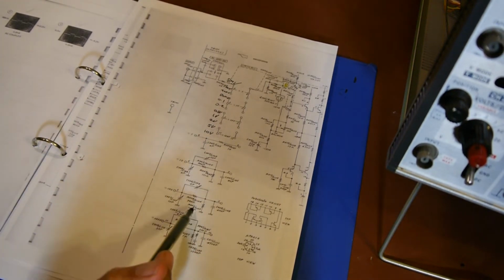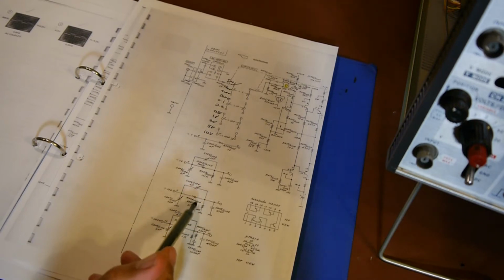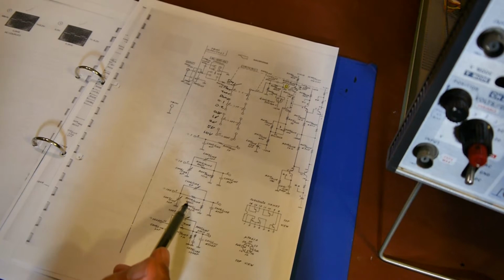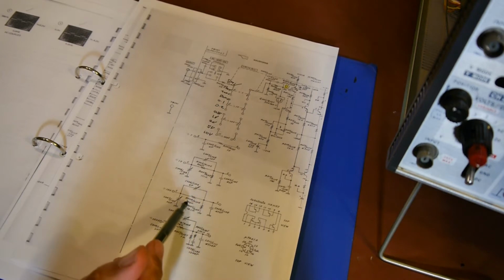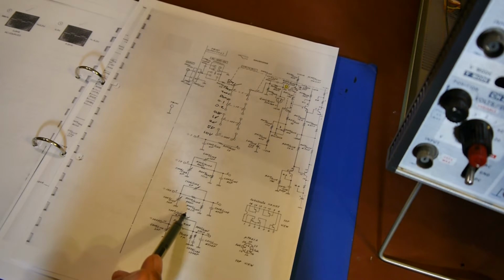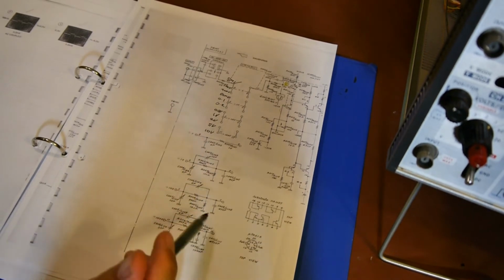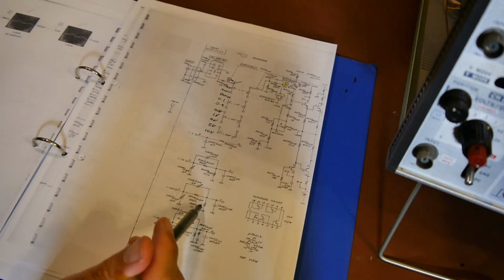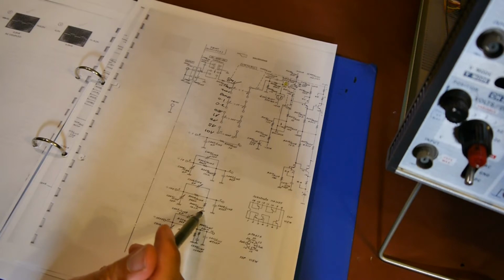So the most obvious thing to me would be to look at this divide by 100 network here. And what I'll do is check these two resistors. I just can't read them on my circuit diagram at the moment. That looks like R004 and R005. So I think the first thing to do is to check the resistance of those. It looks like it should be 990k, and is that 10.1k? Hard to read at the moment. I'll have a closer look at them in a minute. So we're going to check the voltage levels, and also check that we've got the ground connection on the negative side of the voltage divider. I suspect we will have the negative side, because otherwise the voltages would have read high rather than low.